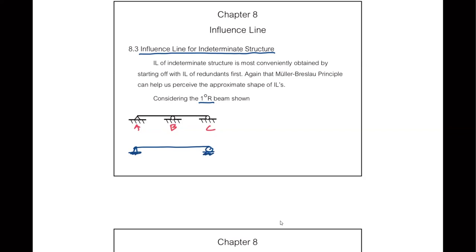Well, the influence line is that you need to apply the unit load anywhere on the structure so that you can calculate the reaction at B. So let's say the common nomenclature is that, if I have the unit load here, and this is applied at the distance X. Now, your beam would deform like that, and we will have deformation. Let's call this delta B.